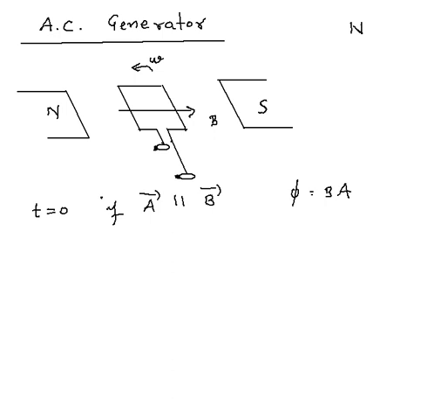But just saying flux is maximum doesn't guarantee EMF to be maximum, because EMF has to do with the rate of change of flux. How quickly flux is changing will decide the magnitude of EMF, not just the value of the flux. In time t, by how many radians will the coil turn?